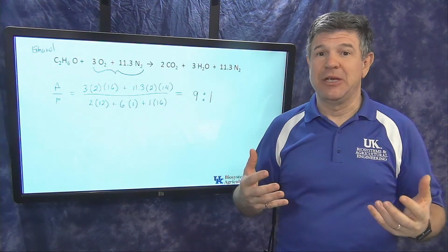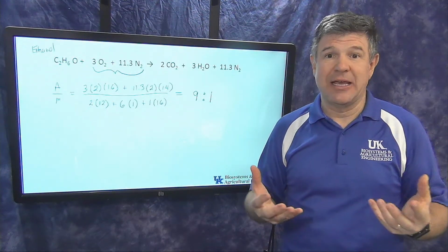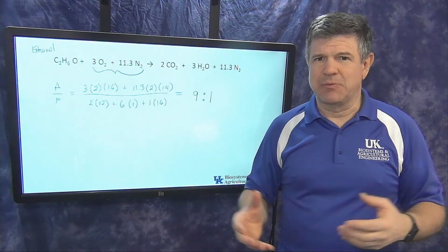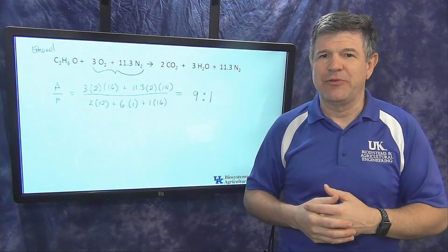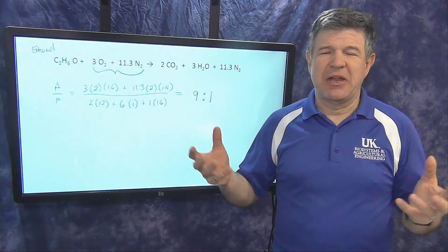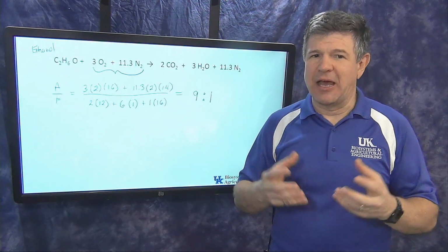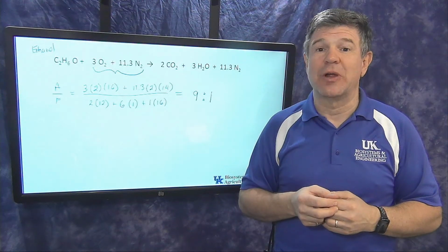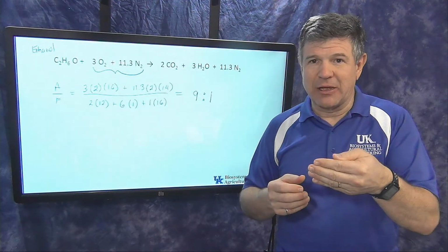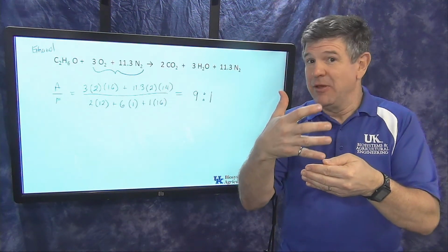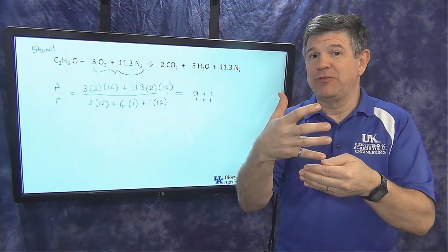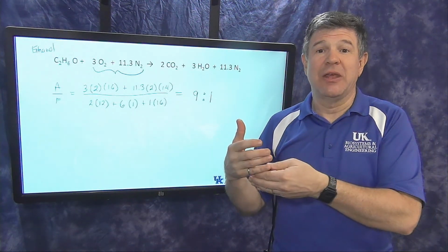Now we can see why I can't take an engine, like a small gas engine that doesn't have any electronics or anything like that in it, where I've got the carburetor set up and tuned for gasoline, so that certain amount of liquid that's coming in is mixing with air at a ratio of 15 to 1 and going into the engine, and it's running well.